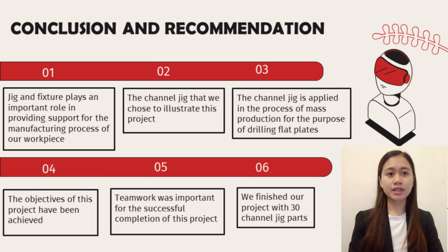Furthermore, the channel jig is applied in the process of mass production for the purpose of drilling flat plates. During assembly, a channel and a screw clamp are used to hold the workpiece in place, and a locator is placed on the component to show where it is in relation to the jig. To summarize, the objectives of this project have been achieved.